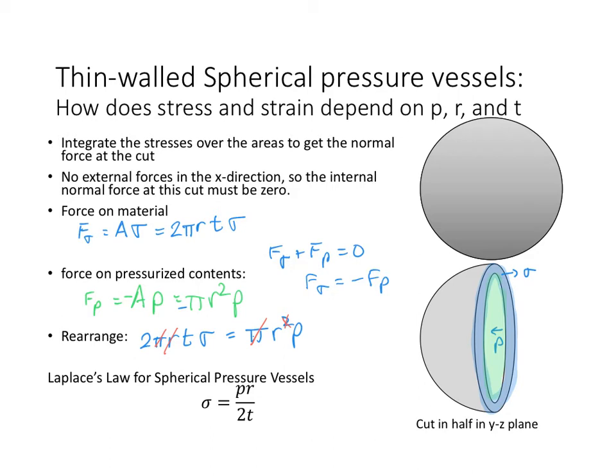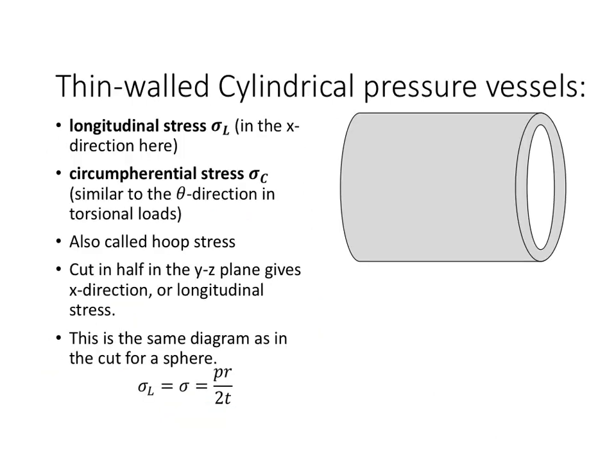And so then we rearrange that to say what we see down here, which is that the stress is equal to P times R divided by 2T. We refer to this as Laplace's law for spherical pressure vessels. So we're also interested in